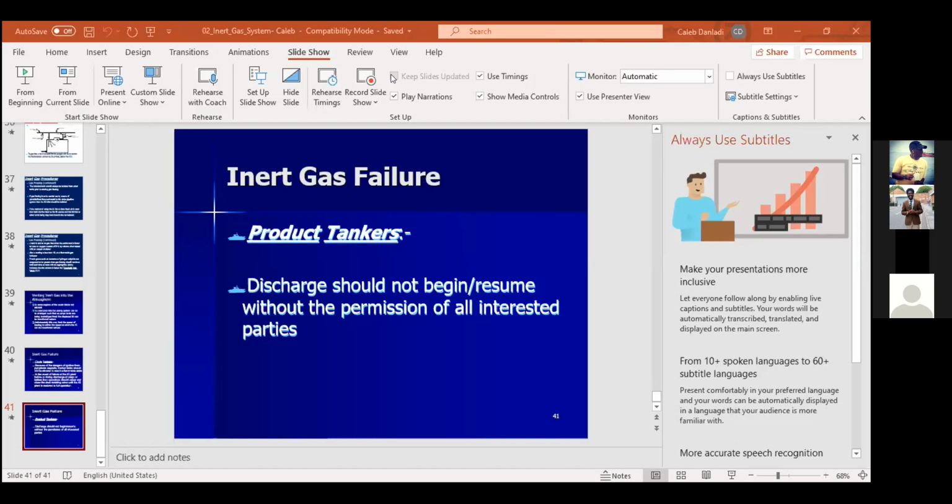But sorry, I actually really want to understand. If the gas is supplied from ashore, how then does it develop pressure to work in the tank? The pressure comes as the inert gas is supplied, right? You connect it, it comes like an uptake from the boiler. You understand? So all your fans are running, everything of yours is running. It's just going through the normal system up to the deck water seal, and the fan is giving you the required pressure you need.